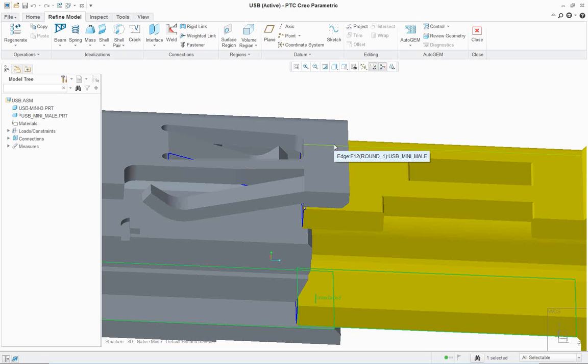But if it's something where you understand that friction is going to be anywhere between 0 and 1, you could just run 2 analyses, one where it's 0.1 and another where it's 0.9. And that can at least get you an understanding of the best and worst case scenarios for how much force you have to design for. And so typically you would find that with the materials. But if you don't have that, you can still run it using worst and best case values in order to understand your design analysis.